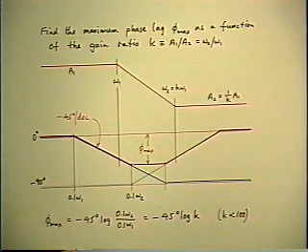It's very frequently used as a compensating network in a feedback amplifier. In a feedback amplifier, looking ahead for a bit, but you know it already, ensuring stability involves meeting the Nyquist stability criterion, which in its simplest form means that you have to prevent the phase lag from getting to 180 degrees while the magnitude of the loop gain is still greater than 1. Otherwise, negative feedback turns to positive with a gain greater than 1, and then you have an oscillation. So basically the stability criterion is to prevent the phase lag from rising to the point of instability.